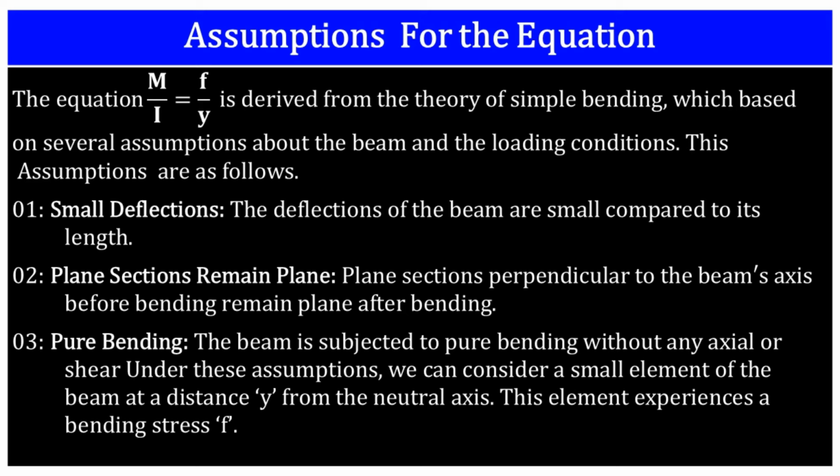Firstly, we assume small deflections, meaning the element bends only slightly under load. Secondly, plane sections perpendicular to the element's axis remain plane after bending. Third assumption, the element is subjected to pure bending without any additional forces. Now we are switching over to the next slide for next 3 assumptions.